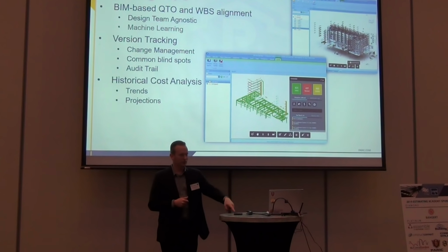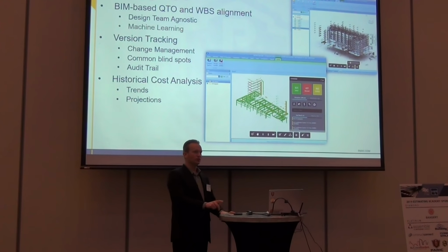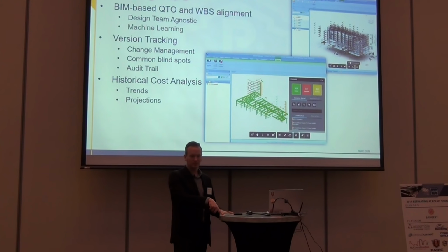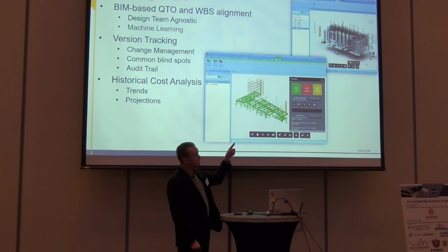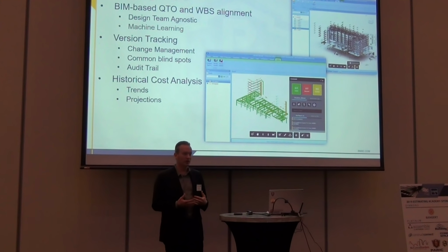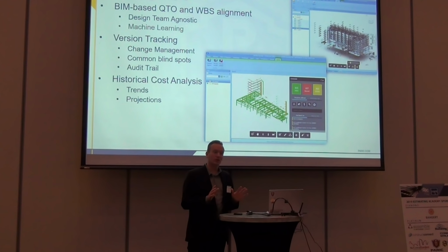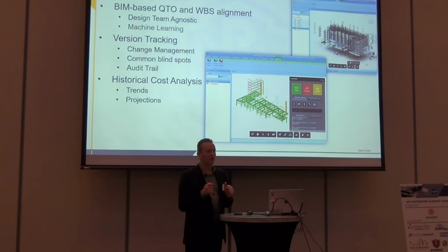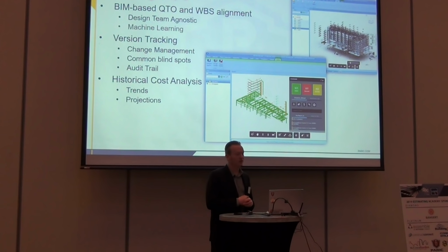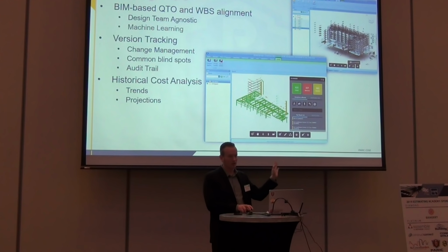Okay? So if you know that's your baseline, when you get the next set of drawings and somebody adds drywall to it, that same GUID updates. Now you know what changed. So the yellow changes a lot, but it helps you understand what's going on with the model. I'm not telling you to necessarily model right. At least you know what's going on with the model. You can ask questions or you can start to dissect it in a different way. This saves a ton of time.